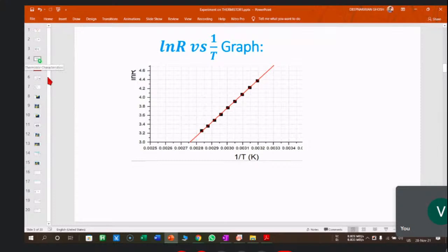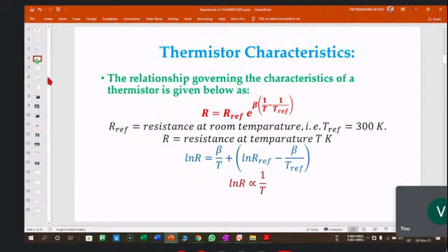Actually, thermistor property depends on the material, not only the material but the content of the material, how much material is there. So that is the problem. And for a thermocouple, only the two metals are useful. I understand, I agree. I'm just interested whether anyone has checked the extent of deviation. I have checked to some extent. Even if you take two thermistors at room temperature, they will have different resistance.